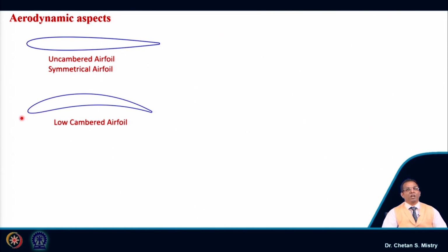Now, I will be giving some curvature to this blade. So, here if you look at my flow, it is entering at some angle, it will be passing through the suction surface and my pressure surface, and later on it will be moving downside towards the trailing edge. This is what we call a low cambered aerofoil. When we put this camber, it gives me the differential pressure on the pressure side as well as on the suction side. That will lead to the lift force, which is very important, and perpendicular to that, what we have defined as the drag force.